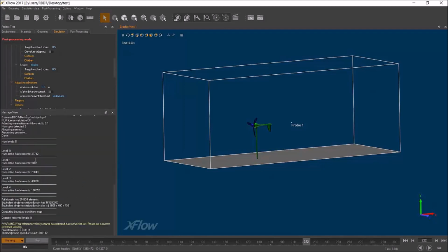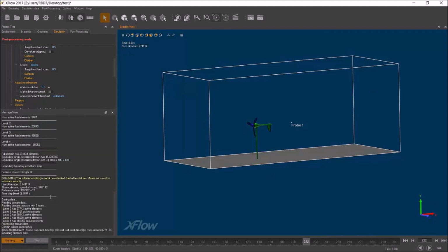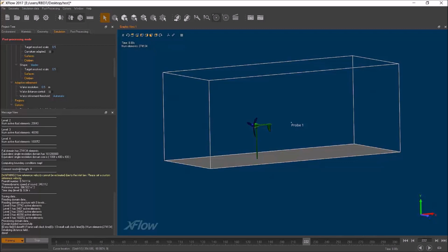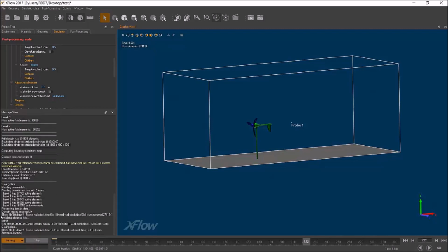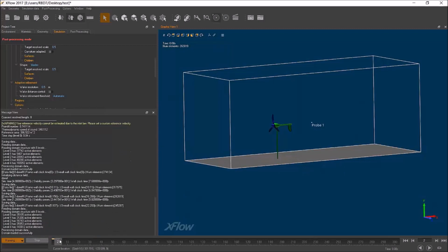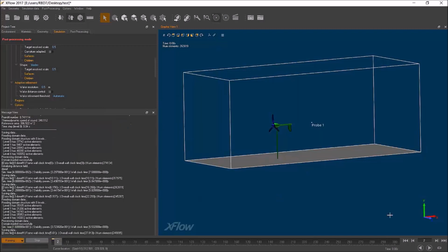And you can see the way it does is it tells you a lot of different messages, logs, okay, which are the domain generator first. I've got 270 elements in that simulation. It all initialized correctly, and then it starts iterating. So I've got my frame number 0 computed, which is the initial frame, and you can see then a few time steps occur, and then frame 1, and then frame 2, and so on. So the simulation will just run, and you see the bar will just fill as it computes and as the frames are being computed. So just in the meantime, my calculation is starting.